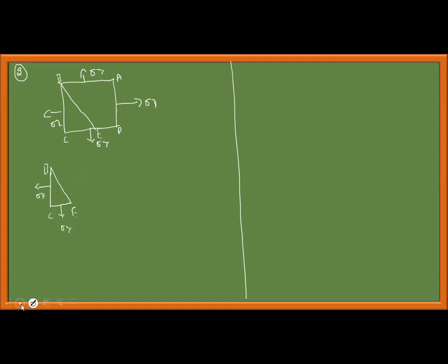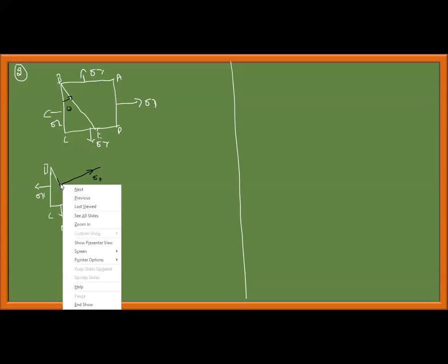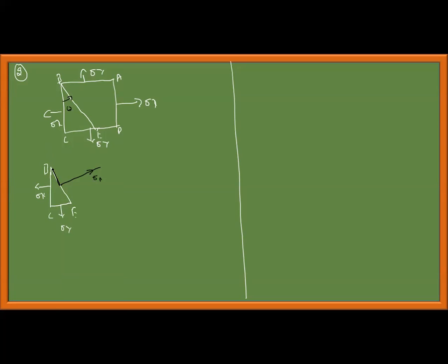For equilibrium, when I take a section like this, this is the plane at a certain angle. When I measure in the anticlockwise direction, this is theta positive. For equilibrium, there should be a normal stress sigma n acting like this, and also a tangential stress sigma t parallel to the plane, acting like this.